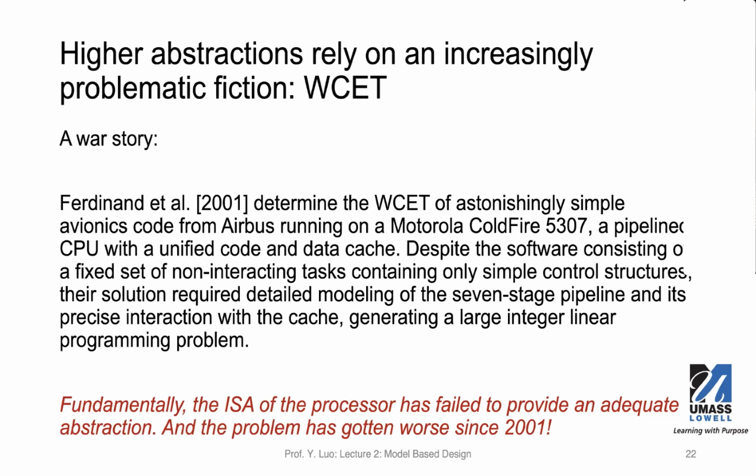So this will affect the worst case execution time that people can assume. And if your design requires strict timing, like this avionics code for airplanes, then this is something you should be very, very careful about.